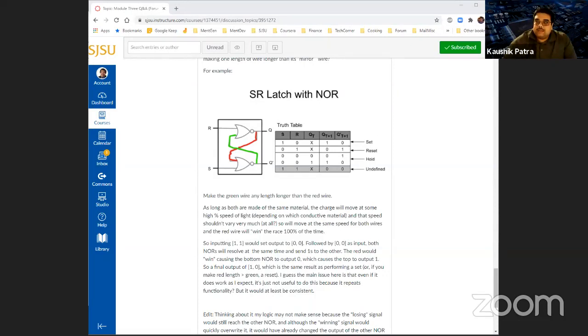Sometimes we need to do that to solve other problems like electromigration, but not necessarily. At least from the digital, synchronous circuit perspective, we don't go for that. We basically want to have more deterministic control over what goes out as output. That's the reason.